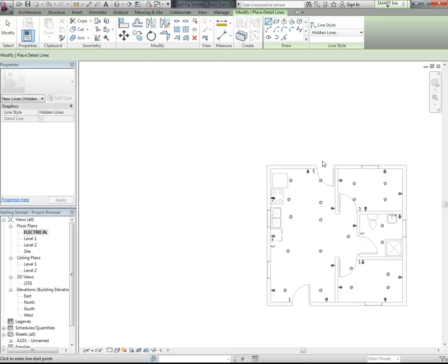That one's fine. So you start at a switch and you say, I want this switch to turn on these lights. Oh, first of all, you want to click the style of line. You want to do a spline. This is a spline. So I'm going to click the switch, click this light, this light, this light, this light, this light, and this light.